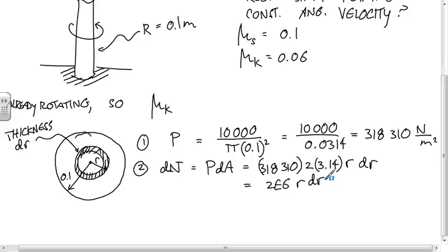Okay. So that's the normal force. What's the next step? Step 3. The next step is sort of a trivial step, but just remember that the thing producing that moment isn't the normal force. That's in the wrong plane. That's perpendicular to what we want. What's producing that is the friction force, which comes from multiplying the coefficient times this.